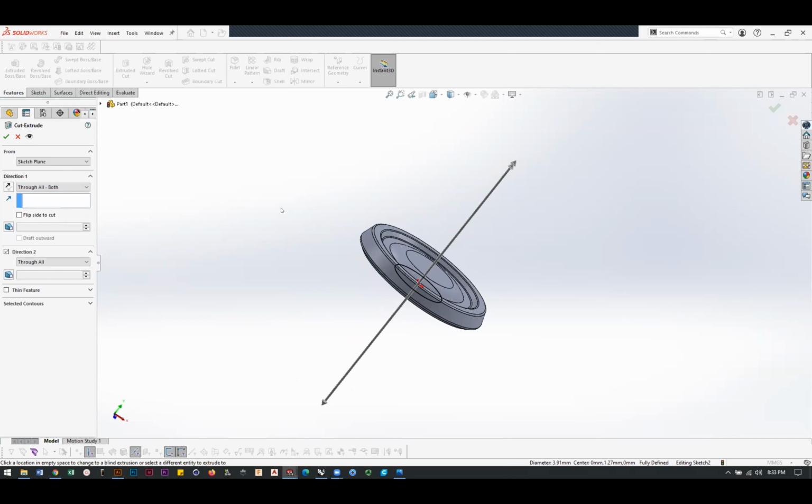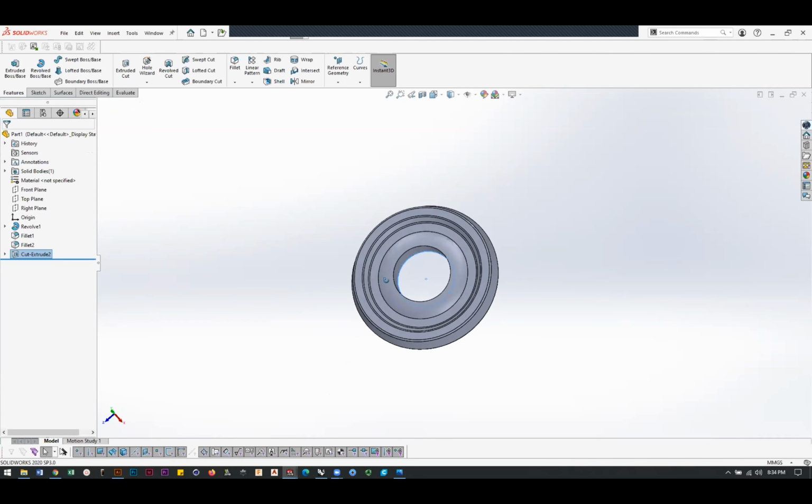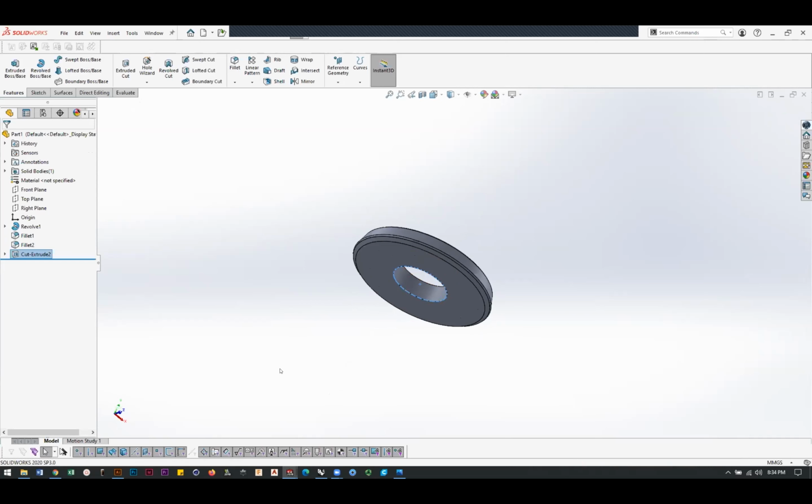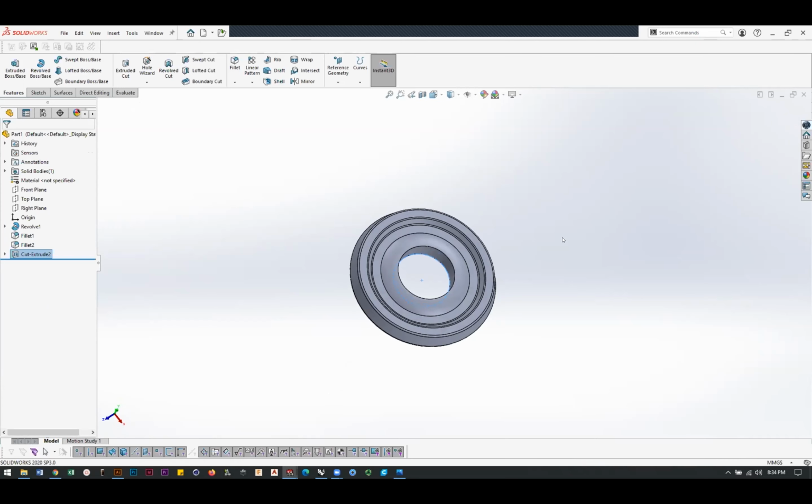It's going to evaluate all the different bits of geometry that could be cut through, and then it's going to cut through all of those pieces. So green checkbox, and it's going to fail. Okay, cool. Now let's just do through all. There we go. I think because there's nothing on one side of the model, saying through all both directions, it was saying it wouldn't work.